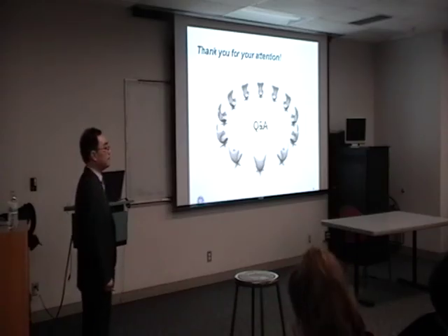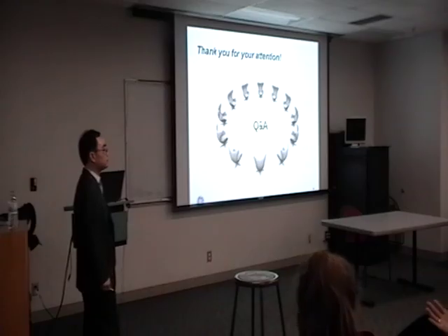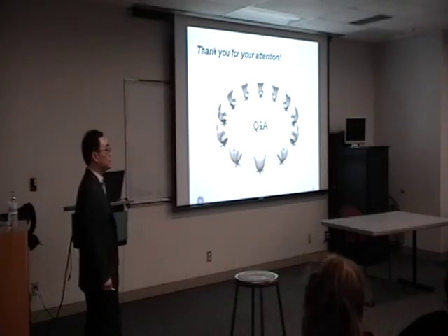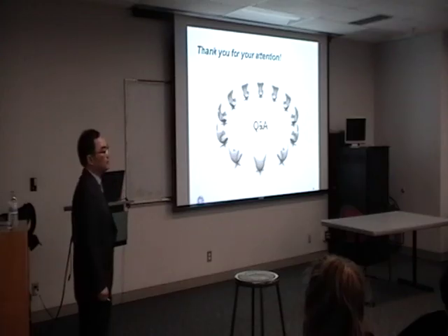Question about the turbine: you showed the turbulent boundary layer interaction with the trailing edge, of course, and that is, I would say, one more difficult part to solve. I think the serrated trailing edge is something we mostly developed empirically. I haven't seen too many computational results from that. Can you comment on that?